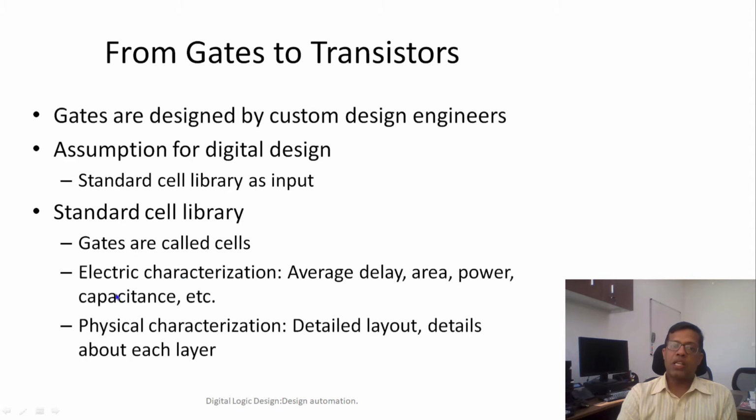For example, electrical characterization, which means that for a particular gate we know the average delay. Characterization will also clearly tell what the delay is when the output goes from high to low, and what the delay is when the output goes from low to high. Similarly, what would be the power consumption in each and every case? What is going to be the area? What is going to be the output capacitance, the input capacitance?